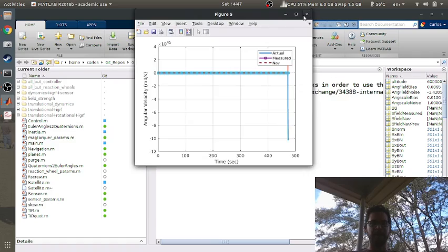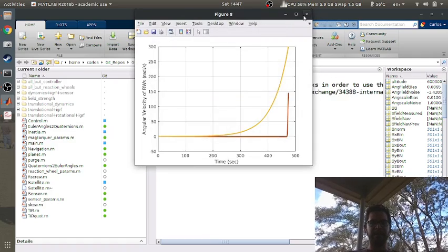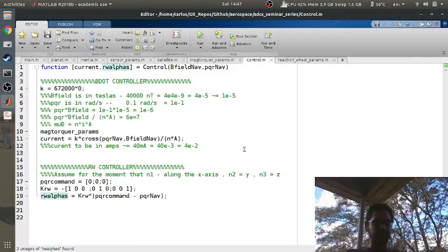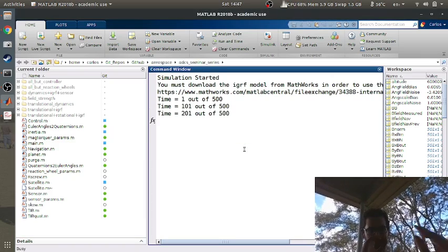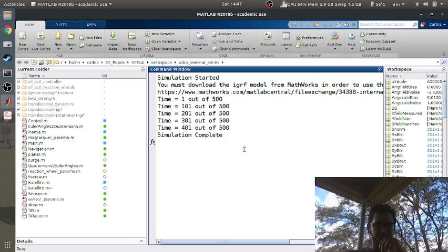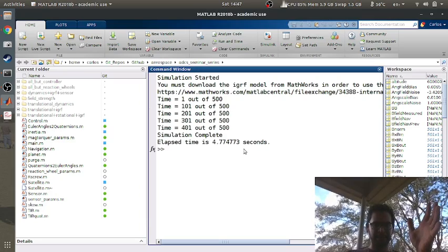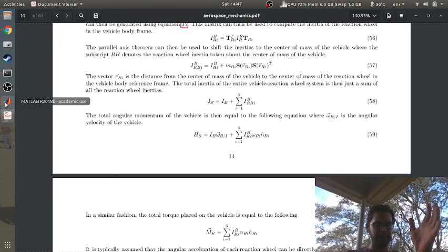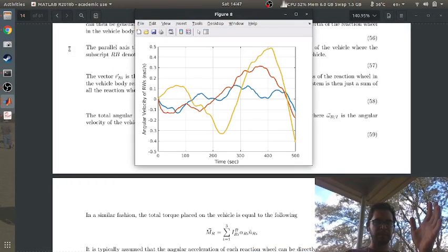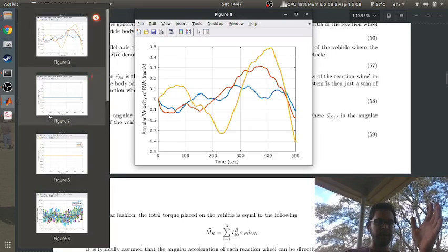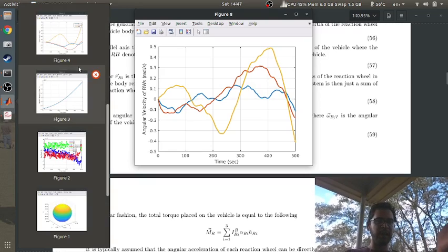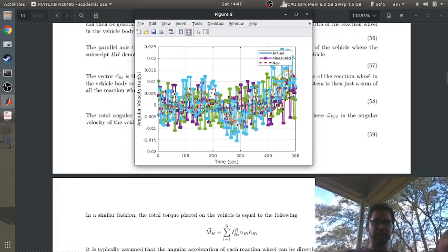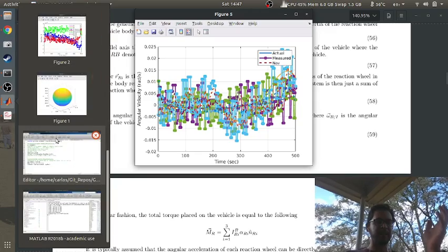Which means my signs are wrong. Yeah, because that shouldn't have happened. Let me get rid of this minus sign. When in doubt, change the sign of your proportional controller. Okay, so nothing should happen. Like, nothing should blow up. Oh! So the reaction wheels are moving, duh, because there's noise in the angular velocity sensor. Yeah, of course. So let's cause this whole thing to spin.